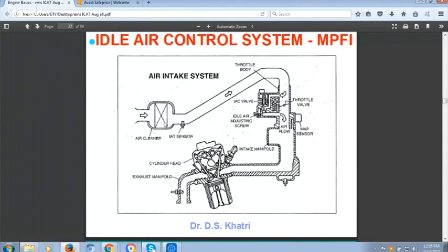So this is the air cleaner. Air is going in, and here it is entering into the engine. So this is the intake manifold passage, right? And now it has one valve. If I am making 2 valves here, are you understanding me? Then this whole passage has to be redesigned and optimized, and the shape of that is very important. So after 6 months of simulation, when we started making the prototype, do you know what type of design came out? The design was like a nose.